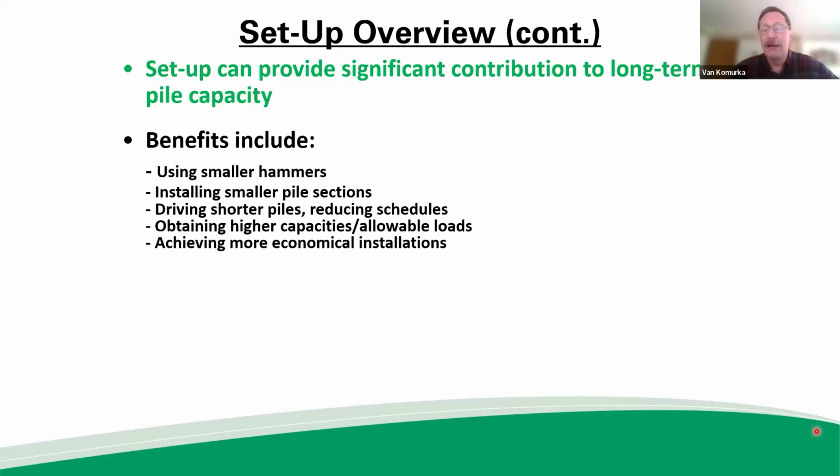By the way, I'll speak and present in terms of allowable stress design terminology, capacities, allowable loads, safety factors. All these concepts are applicable to LRFD as well, but just for ease, we'll just talk in ASD terms. So all of those benefits then result in more economical installations. We talk about setup and test programs in improving or reducing cost, risk, and schedule.